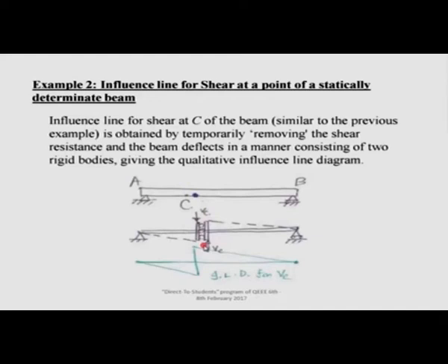That is why we have drawn it this way, and with that this goes down and this goes up. That is actually the positive shear influence line diagram and the negative shear influence line diagram. We will see more of it when we find out the values of the positive and negative shear at different locations, and we will understand what is happening. So, this is what the Muller-Breslau principle can offer to you while drawing the influence line diagram for different structures.